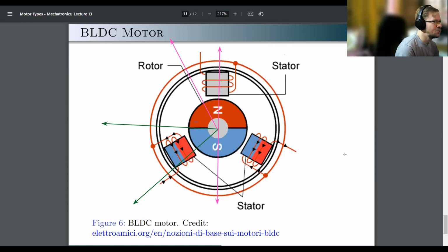This implies you have to know where your rotor is. That is not what we had to do with the DC motor. And by clever design, we could avoid it with other motors. Stepping motors, they generate orientation. So almost by definition, you more or less know where you are. And if you don't know, you just go once, one full cycle, and you'll be fine.